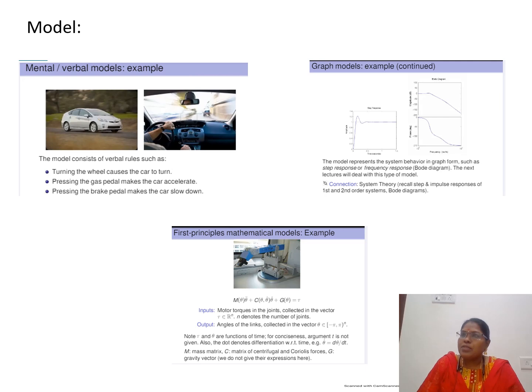For frequency and time domain, we have used the root locus for time, and for frequency, we have used the Bode plot. From the Bode plot, you will get some responses. From the time domain analysis, you can find the rise time, peak time, settling time, and how much error you have. All these things you can calculate from the simulation results.